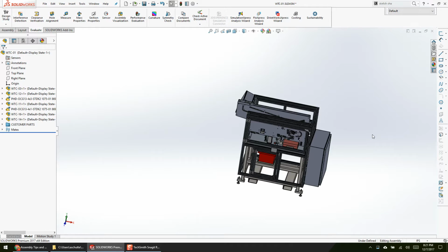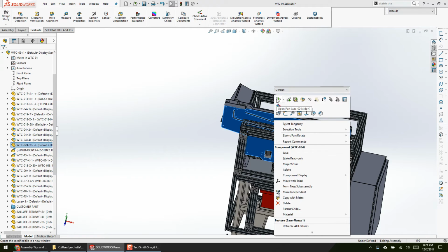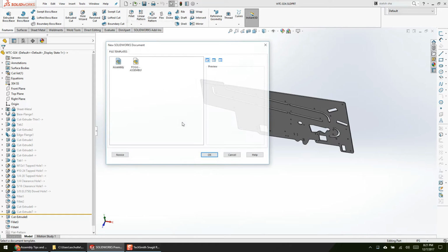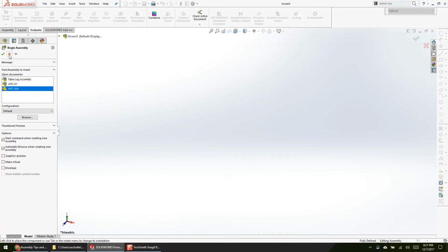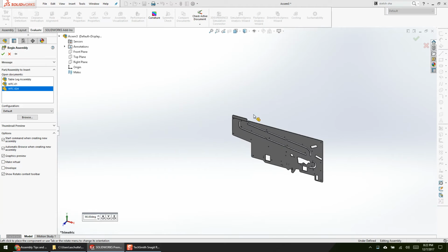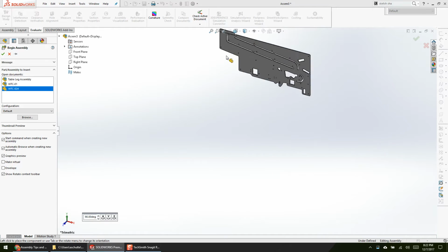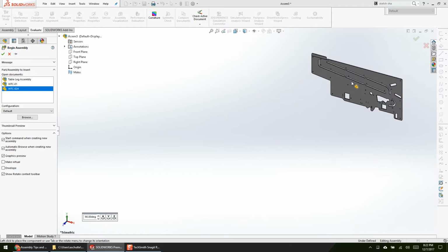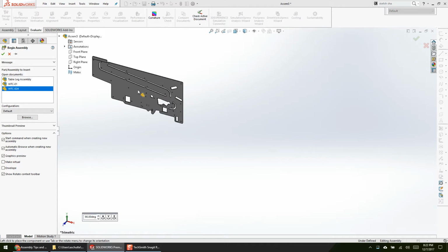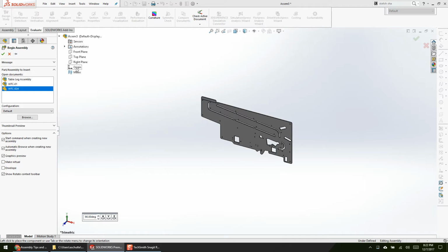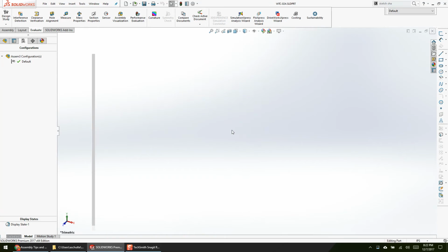Well, it aligns the origins. Oh, okay. The origin of the part and the origin of the assembly. We'll see, I think I used a big assembly, so it didn't give me a preview. If you don't have the preview, the first plane, your normal plane, the whole thing is going to be spun around somewhere. So like here, no matter wherever I click, it's going to place it randomly there. If I hover over my origin, it snaps to my origin. Or if I hover over my green check, it snaps to my origin. So it's just going to geometrically go there, but it's fixed in arbitrary space. That's not a reliable assumption standpoint.